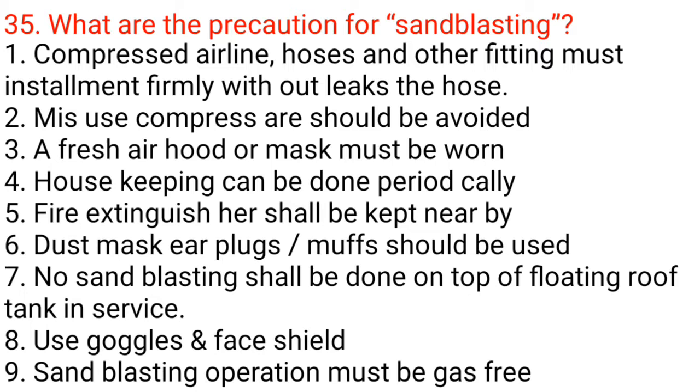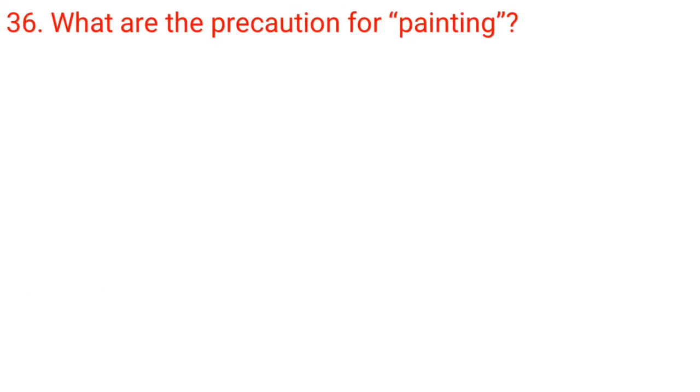7. No sandblasting shall be done on top of floating roof tank in service. 8. Use goggles and face shield. 9. Sandblasting operation must be gas-free.